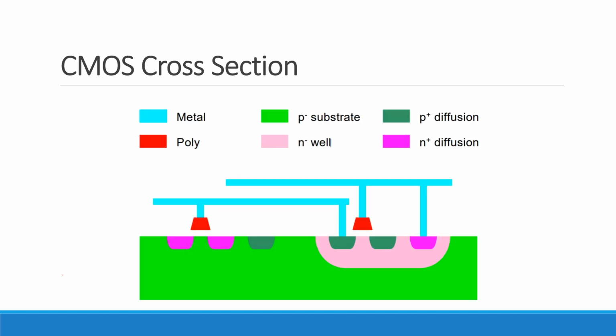So before we dive into the core of the discussion today, I just wanted to level set everybody, to make sure everyone's on the same page about what I mean by a CMOS process technology. The point here is we're talking about a single-well CMOS process. There's a P substrate where you form your NMOS transistors. There's an N well where you form the PMOS transistors, but there's just that one P substrate for everybody.